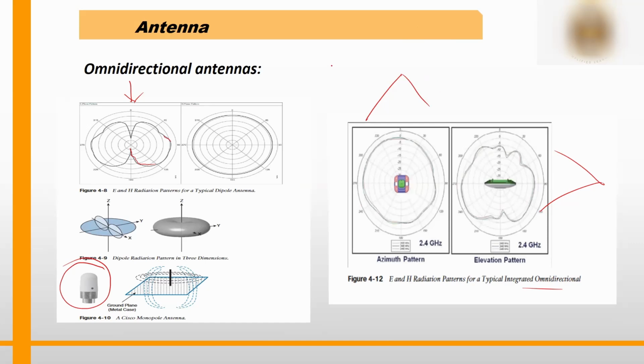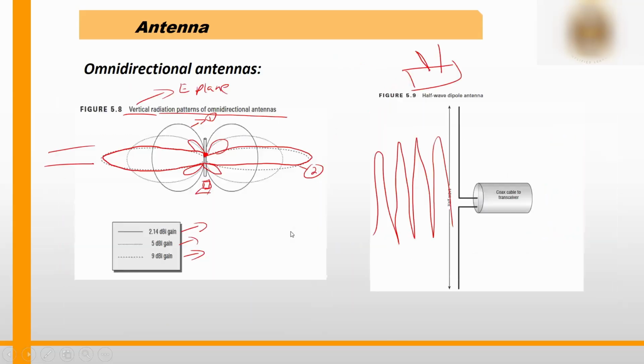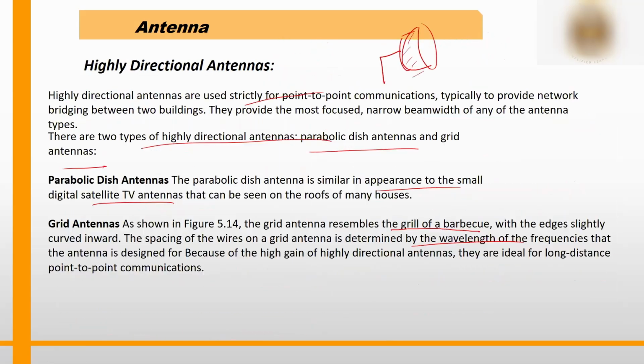Whenever you are referring to an antenna, it is like I for internal and E for external antenna. This one here is a monopole antenna, and you can see its radiation pattern, which is omnidirectional. The azimuth pattern is what you see when you look from the top. The elevation pattern is what you see when you look from the side. And I have told you how to calculate these values of dB. I hope that part is clear.